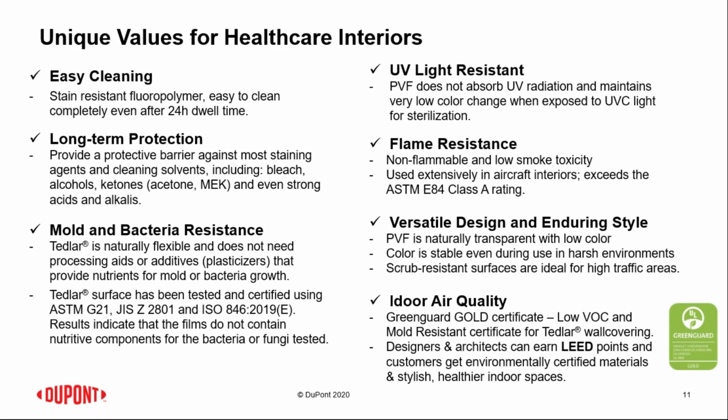Now for indoor air quality, our DuPont Tedlar wall covering film is actually GreenGuard Gold certified for both VOCs and for the mold resistance. For VOCs, what we found is that the Tedlar film can actually act as a barrier to release of VOCs from materials that it's laminated on top of, and can actually improve materials' performance in these GreenGuard air quality tests.